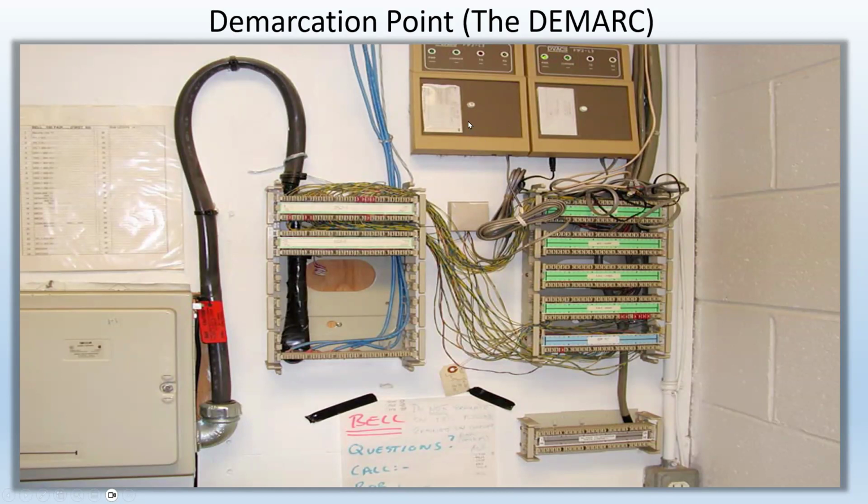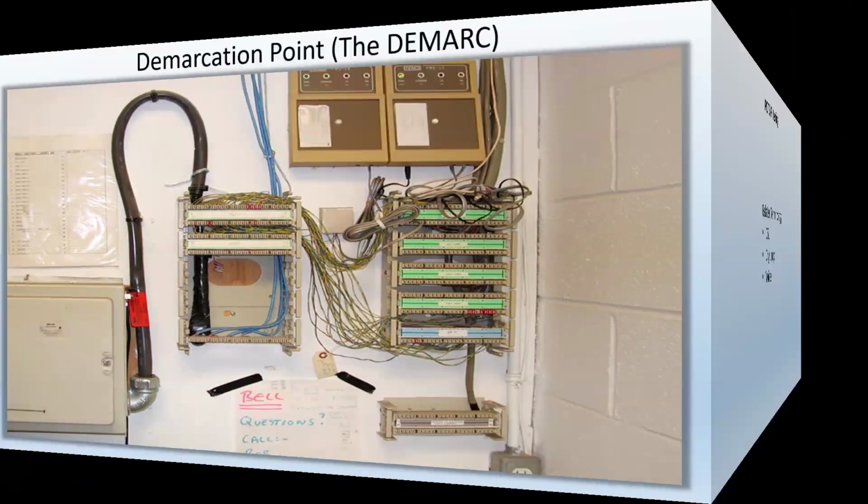It utilizes a couple of pairs, like each of the modems, to modulate the signal for multiple telephone lines. So on four conductors or 2 pairs, you can have something like, I'm not sure, 12 lines, the equivalent of 12 lines. So it's modulated on that side and it's demodulated and it's punched into here, so you can actually have those lines. So here's a couple of modems, and they're called T1s in North America. T1 and E1 are the same idea, but the specifications are slightly different, so that's why we distinguish T1s from E1s.